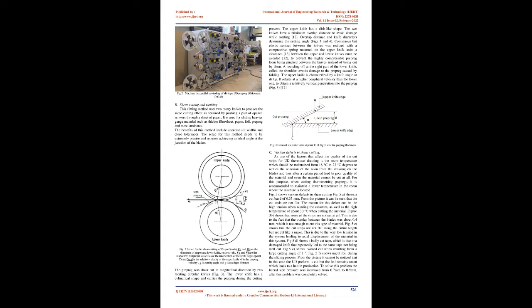Type 3: UD thermoset prepreg type TCR T700SC12K50C, weight 186 GSM, thickness 0.22 mm, and Type 4: UD thermoset prepreg type Hexcel M21/34%/UD194/IMA12K/300ATL, weight 294 GSM, thickness 0.2 mm. B. Shear cutting and working. C. Various defects in shear cutting. D. Several factors. UD prepregs have been provided by the laboratories of IACR Prilep, RN Macedonia.